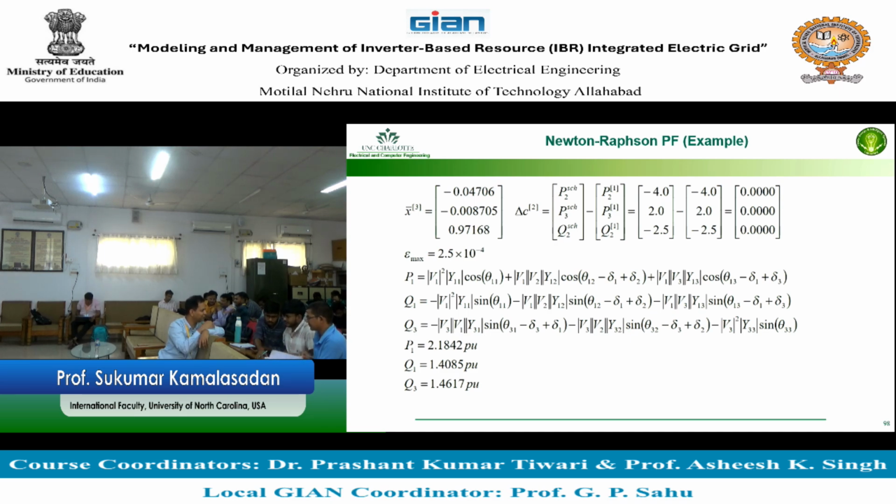Think about the same feeder which you have. At that point you have an EV charging, right? The EV charging is taking power. Load is taking power. The PV, suppose it is giving power. I am assuming there is a battery too. Whatever is giving minus whatever is taking should be equal to 0. The sum of those should be minimum. That is the objective. So you write an objective function like that.